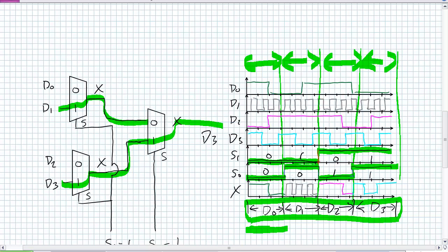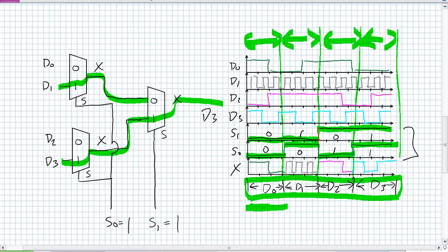What I'm doing is basically time division multiplexing. All those inputs, D0, D1, D2, D3, get time portion use of that particular serial passageway. In this particular case, since there are equal time increments, it's just going to go in this cycle: D0, D1, D2, D3, back to D0, and so on and so forth. But understand that I could have any arrangement of those S1, S0s. Hopefully you understood the example problem here.